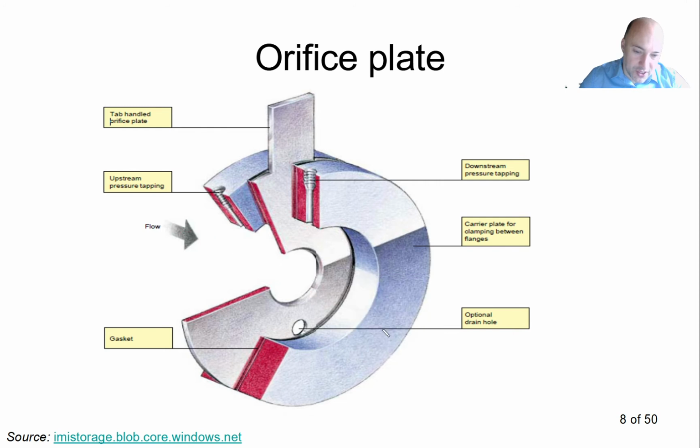Now sometimes there might be some impurities in liquids, so here we may have a very small optional drain hole that allows us to drain the installation and eventually remove some impurities from time to time. But in general, the orifice plate is good only for clean, non-abrasive media.